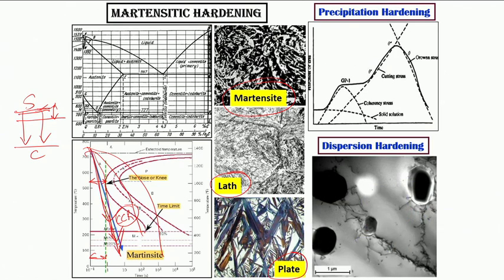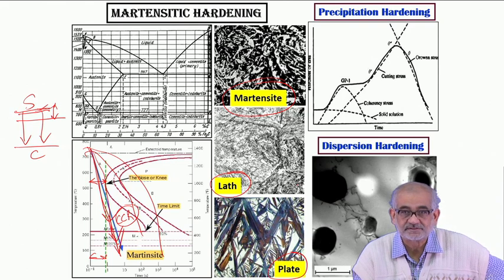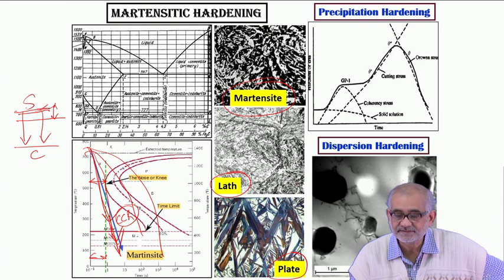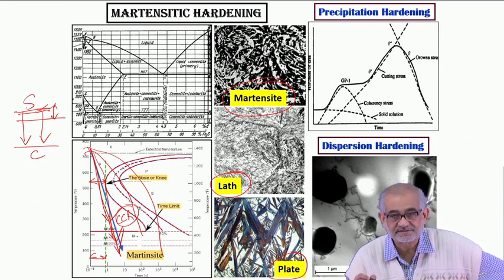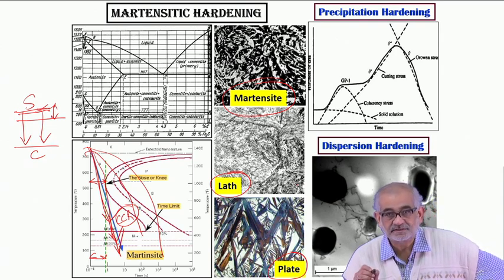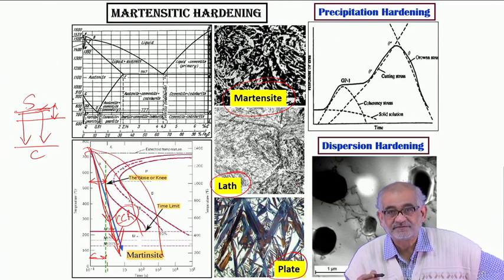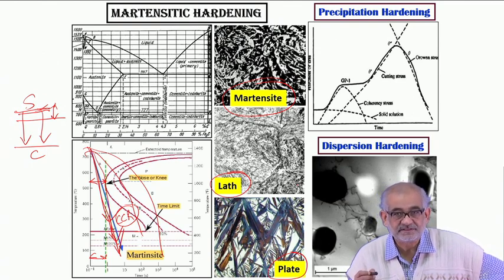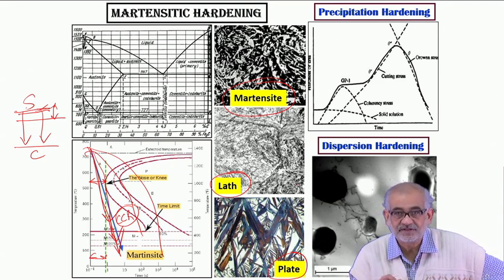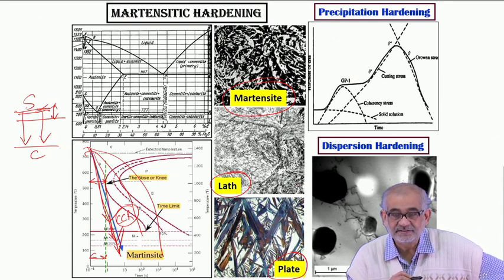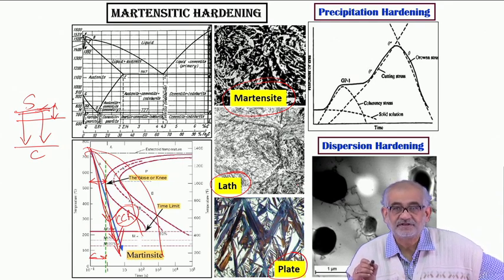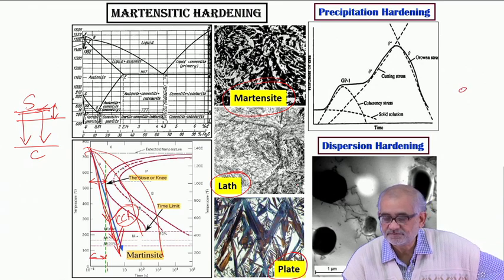In addition, when we talk of carburizing, it's all about martensite. The strength comes from martensite, nothing else. But when we talk of nitriding, of course we have precipitates, in ultra fine condition, for example at the very beginning, or if the nitriding period is very small, or if for whatever reason we are able to create a condition with a very high nucleation rate but very small growth rate. That means we form a precipitate, a nitride, but we don't allow it to grow.